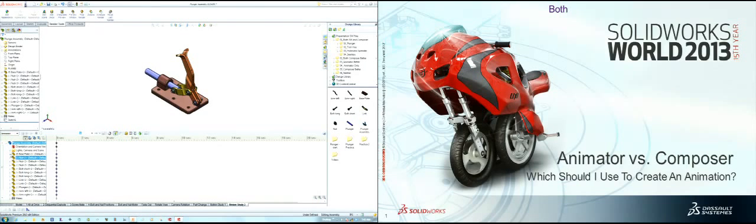Now, one of the most significant differences between these two programs when we come to non-physics-based animations is in SolidWorks, mates are solved. In Composer, there are no mates. So that can be a blessing and a curse, depending on what it is you're doing. So if I want to do the explode on this assembly, the first thing I have to do is make sure all my mates are suppressed. Because if any mates are active, like these down here, things are not going to move. So I need to suppress mates, and that will allow me to come in here and move components.